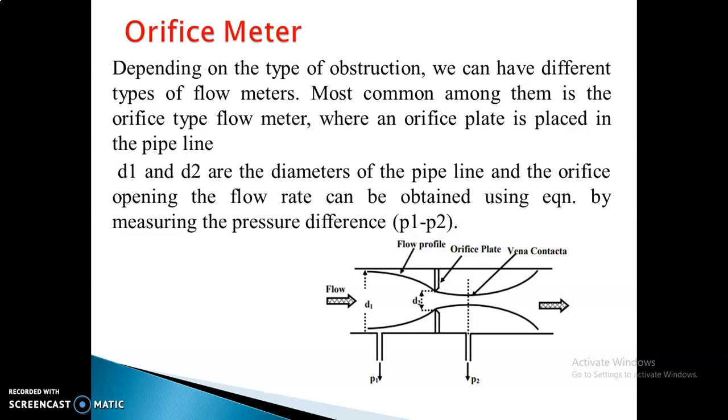That is what we discussed in the previous part 1 video. Vena contracta is nothing but the minimum cross-sectional area of the fluid obtained at downstream. That means this portion is upstream and this portion is downstream. The point downstream from the orifice edge where the fluid area is minimum is called the vena contracta. In upstream there is a converging of fluid, and in downstream there is a diverging of fluid.